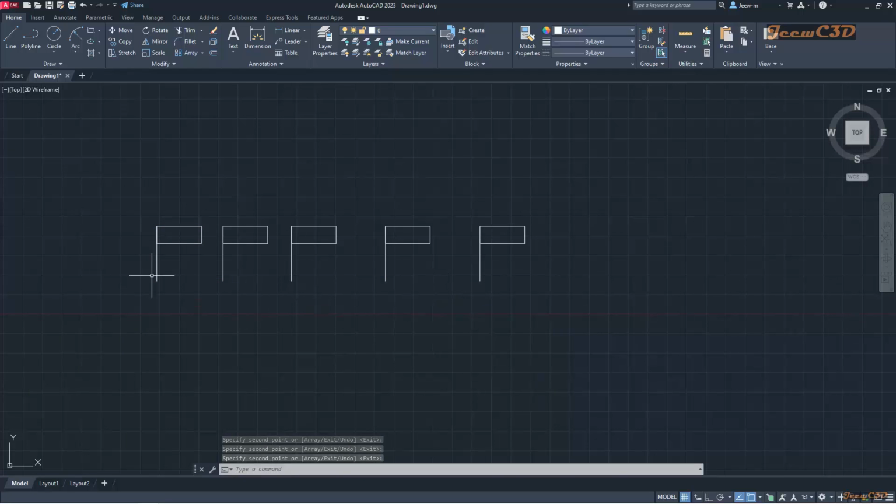So let us say I need this rectangle to have as a copy on the other side. So you need to have the same rectangle to the other side. Since you don't know the dimensions, it is a little bit cumbersome at this stage. So in this kind of situation, we use the command called mirror. It is like a mirror because it is the complete opposite side. Inside the mirror, you can see the complete opposite of what is in front of the mirror.